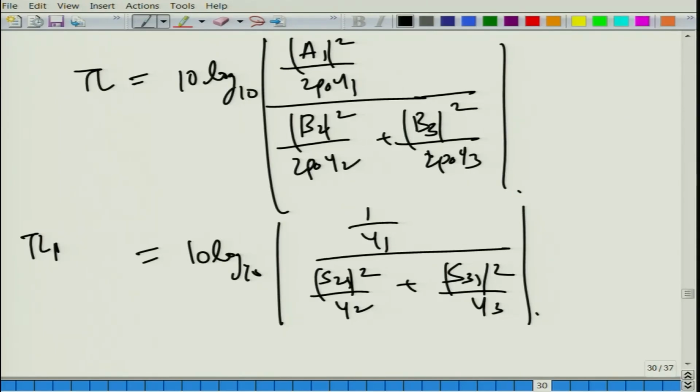In general, you can find the transmission loss for a single inlet and multiple outlet system by these scattering matrix expressions, and trust me, these S matrix parameters get very nasty once you increase the number of ports. So I would just evaluate them numerically rather than finding conditions under which you get peaks or attenuation troughs. With this discussion I will close off lecture 1 of week 11.